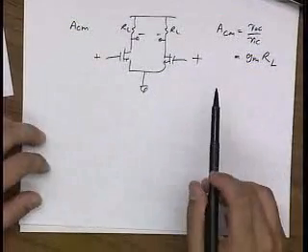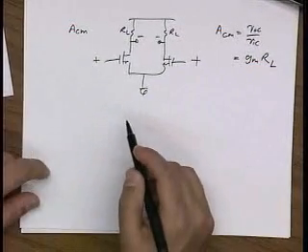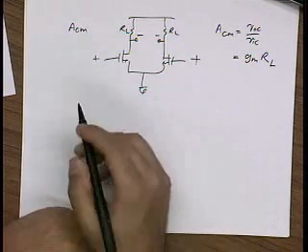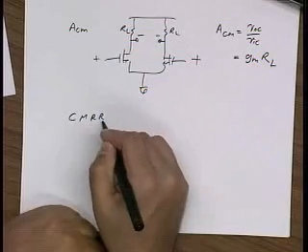You might even argue that the current source not only requires headroom, but also is going to add noise to the circuit, right? So why use that current source? If common mode gain is higher, then common mode to differential mode gain will be higher too. Okay, so what I care about is common mode rejection, right?